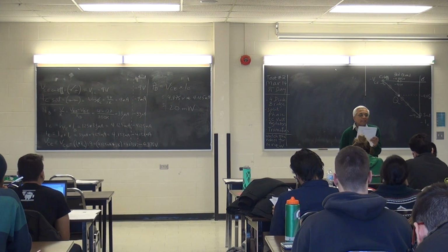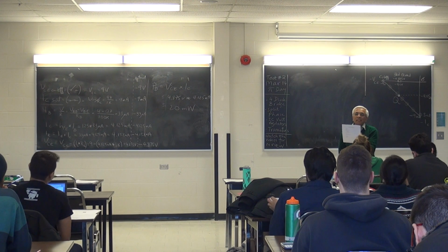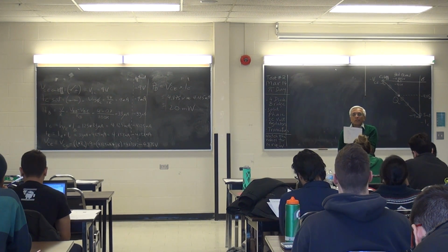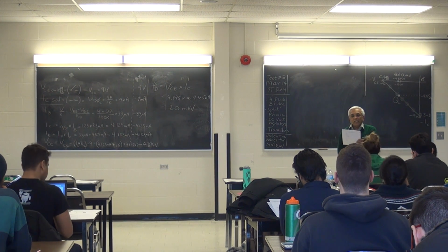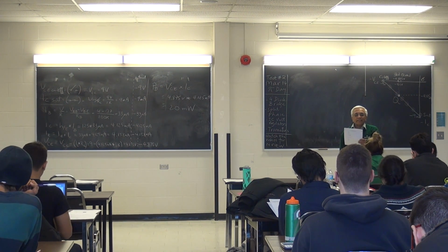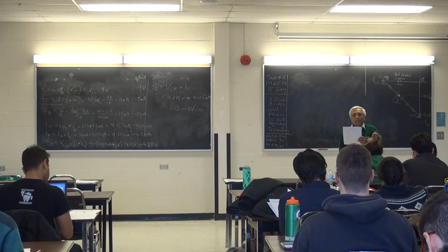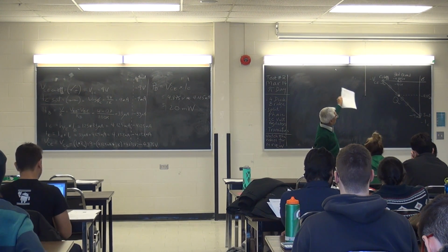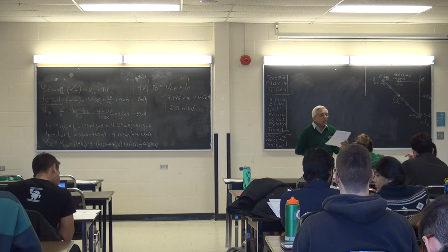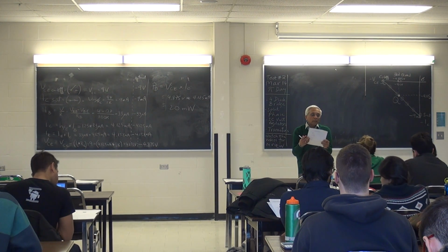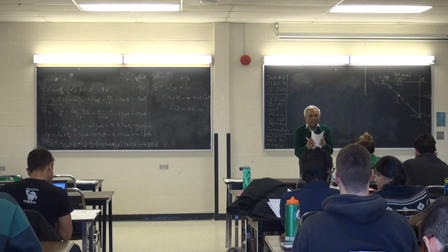So note 2 says, biasing a transistor circuit means designing it for the proper value of the DC, VCE and IC, and setting a proper operating point on the DC load line. So there's my load line. Finding a Q point on it is called properly biasing.